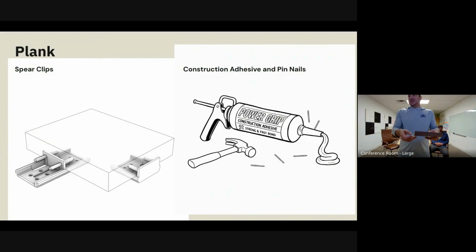All you do is push it against the side, and it pops right in. So you'll put your first one, the end clip, up, and then attach all the clips you need on the other panel, slide it up there, put it in, and then drill your hole in here and do your next plank. And so it goes together.